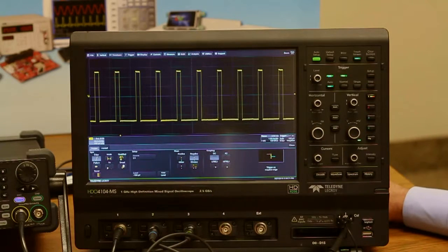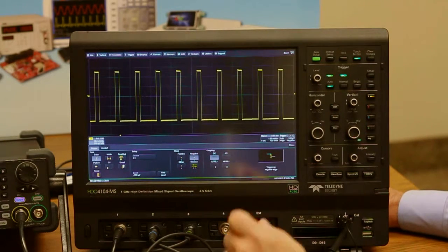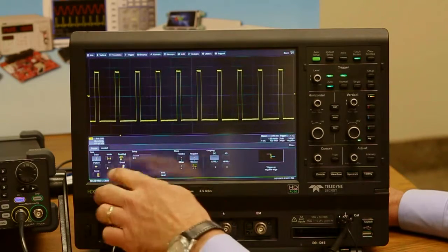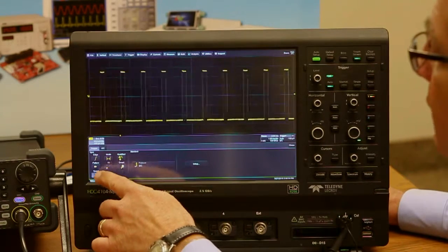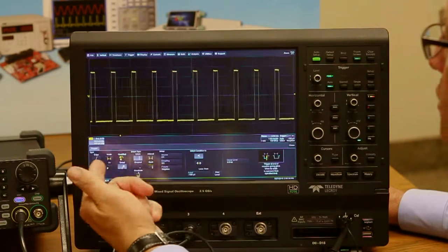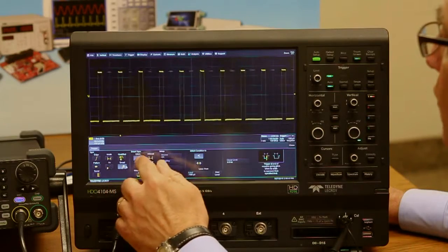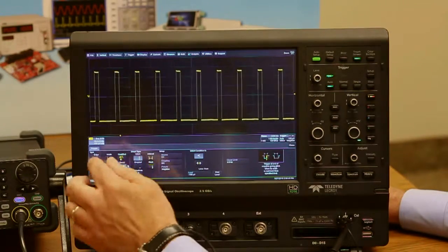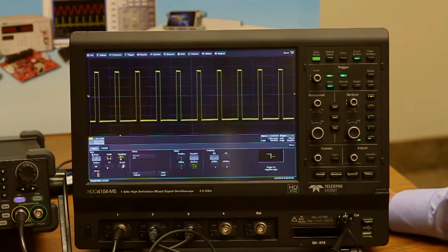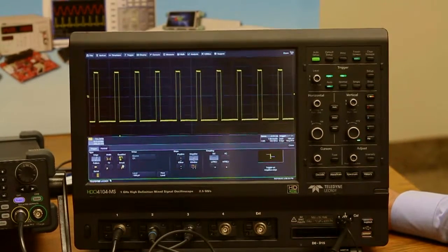All the triggering you need is right here, whether it be a simple edge trigger with or without hold off, a qualified trigger, which triggers on one channel but only after you've seen something else occur in another, or serial triggers. In our smart triggers, you can also look at glitches, intervals, runts and dropouts, or dV/dt, dI/dt, and how, for example, a MOSFET turns off. Triggering within a range of certain values is all done in the trigger menu.